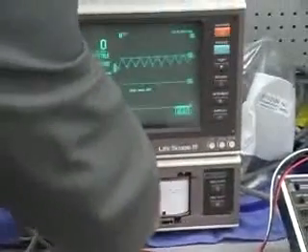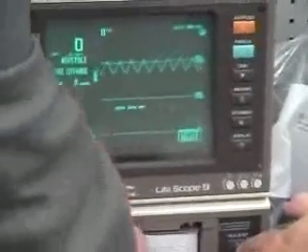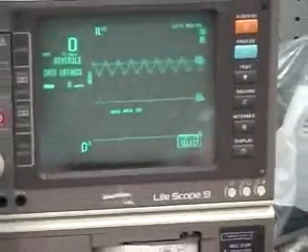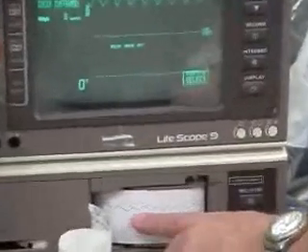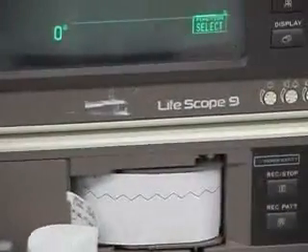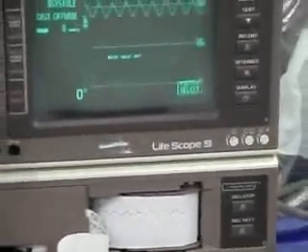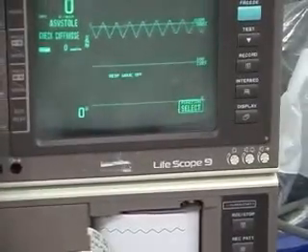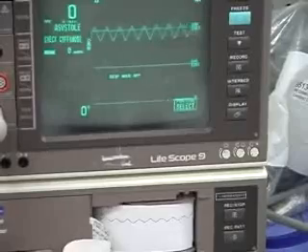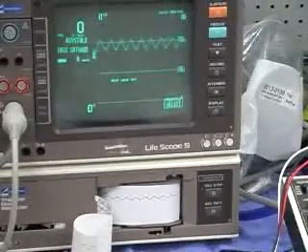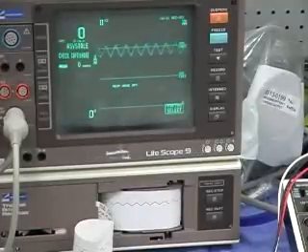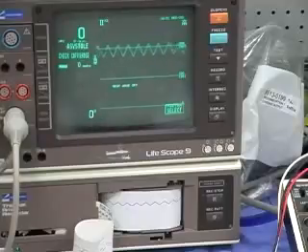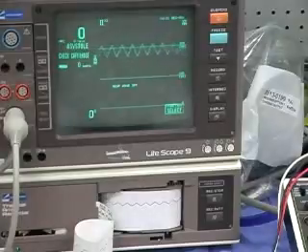Now triangle waves are basically for looking at the span or the range of amplitude. You're looking for the quality of the trace, and if you're losing any bits in your A to D converter. This looks okay. And then sine waves, we're doing different frequency response breakpoints. We have very low frequency sine waves for your low end frequency response, and then we also have some higher ones here too.